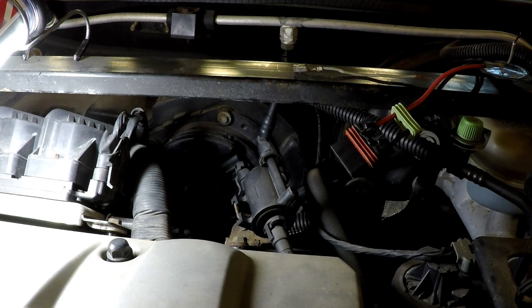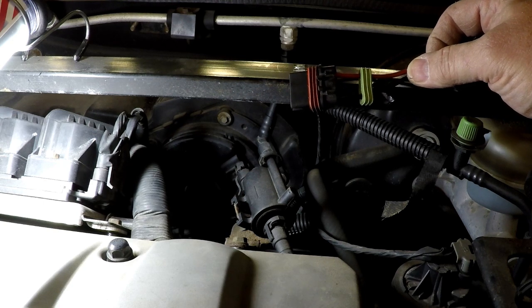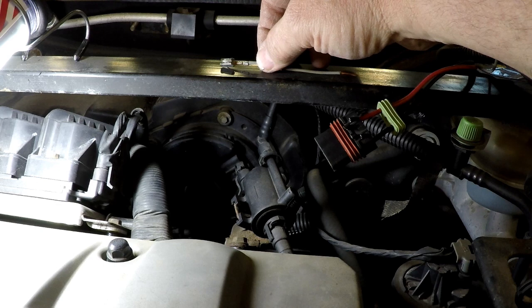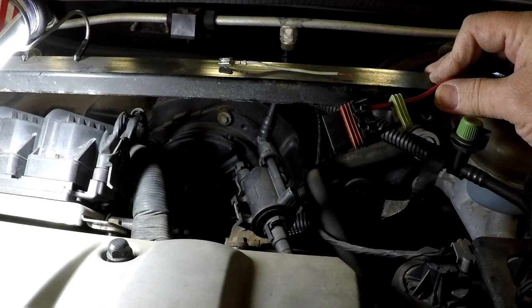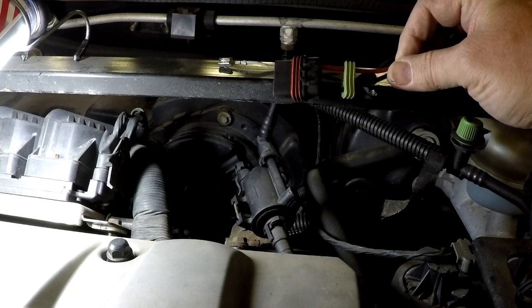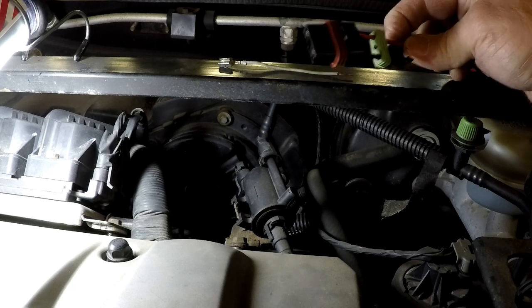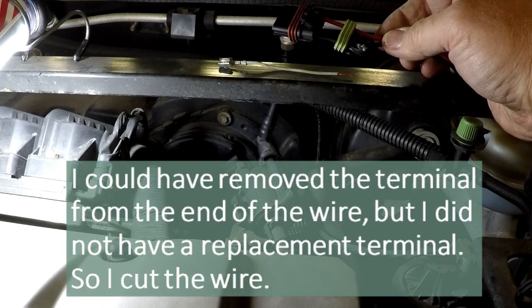All right, I depinned the connector. And I did what I did not want to do. I know a lot of times guys will simply snip a wire and then repair it later to see if they fixed the problem. I don't particularly care for that, at least not teaching it. Real world, it happens all the time, but I had to do it mostly because this type of connector has the stupid terminals come out from the front. It doesn't come out from the back. So in order for me to remove the wire to isolate it from the circuit, I had to cut it. So anyways, there it is.